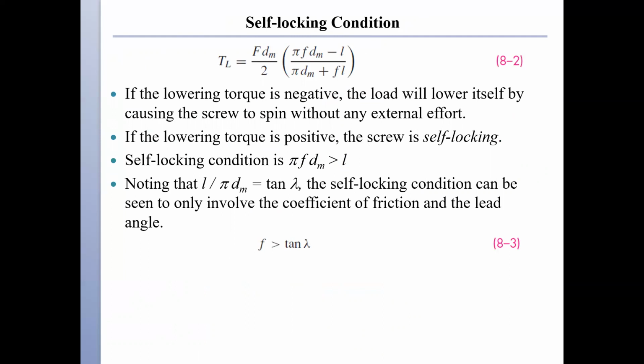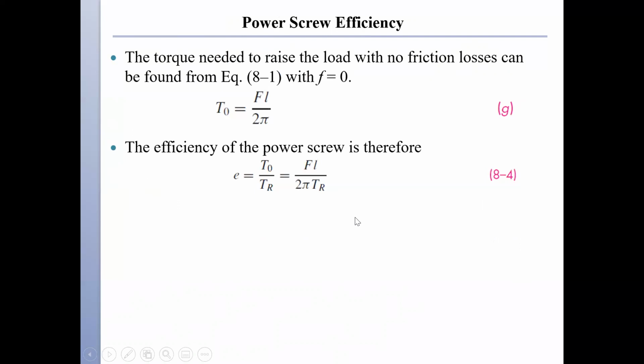And we looked at the self-locking condition, and we learned that if I have a force sitting on a power screw, it is going to be in a self-locking condition if the friction is greater than tan lambda.